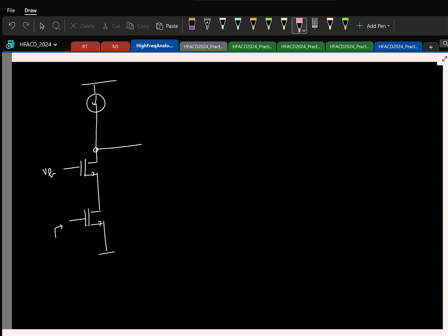So again, let's start with finding the short circuit noise current. Incrementally this is open. I'll find the short circuit noise current. This is shorted. For finding the voltage, the input is applied to the gate. Input impedance is infinity because gate capacitance is not considered. So only voltage is required, and for finding the voltage, I'm shorting the input. So again, VB is incrementally short.